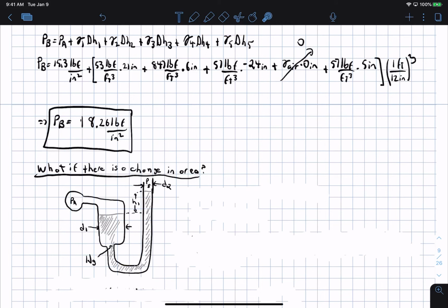We're going to assume it's a tube. And now, even though this tube area here is bigger than this tube area here, the hydrostatic equilibrium condition still applies. The fact that this tube here is bigger diameter than it is over here has no bearing on the change of height at the static equilibrium condition.